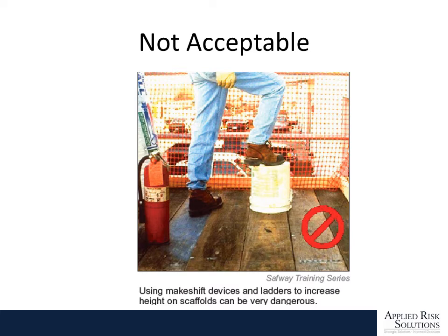When you're working on a scaffold, never use a ladder or stand on anything to gain some extra height. If you do, you're negating the impact of that top rail, and if you were to slip and fall, there's a high probability that you would go over the edge.